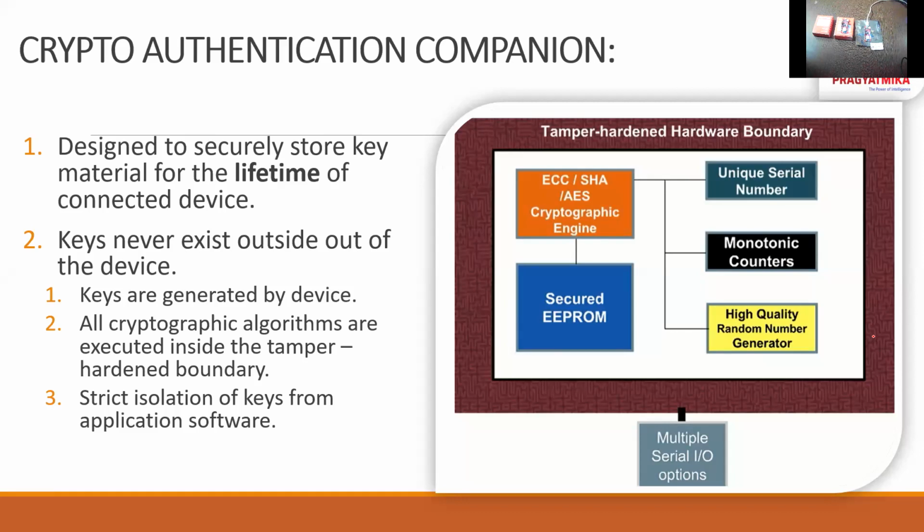So even the ESP and Arduino based microcontrollers, which are not safe for the working, can have this crypto element attached, and you can make your project secure. So that's the role of any crypto element: giving the security. It is in the hardware layer, it is there on your PCB, but it gives the complete security of the communication up to your cloud level of communication.